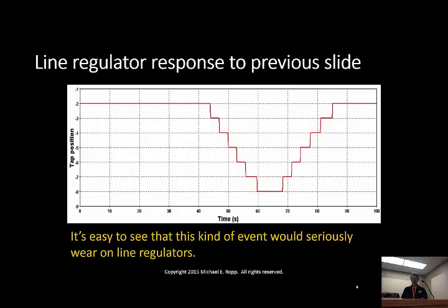That is an excellent question. The question is, back in the day, you're talking about the DC to AC power ratio in the PV plant. And what we used to do is that the DC power rating of the PV array was on the order of about the same as the AC power output rating of the inverter. So you would end up with roughly 1-to-1, maybe about 1.1-to-1 ratio. Now we're seeing much higher DC to AC ratios, 1.5, 1.6. And the question was, well, as I raise that DC to AC ratio, does that mitigate this? And the answer is yes, it does.